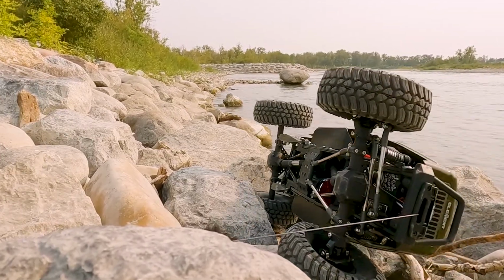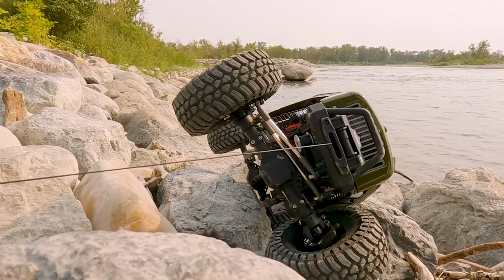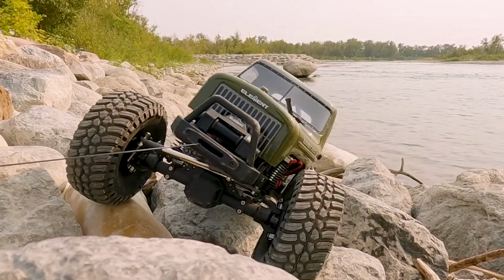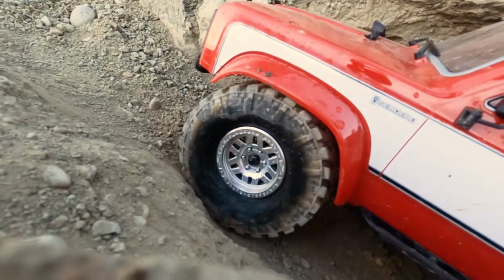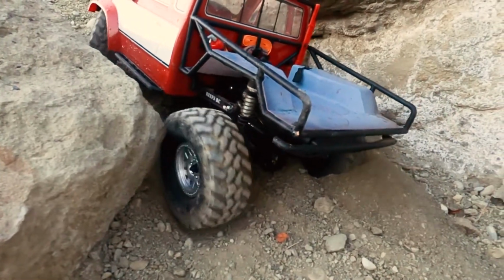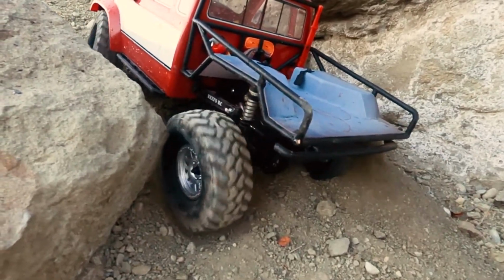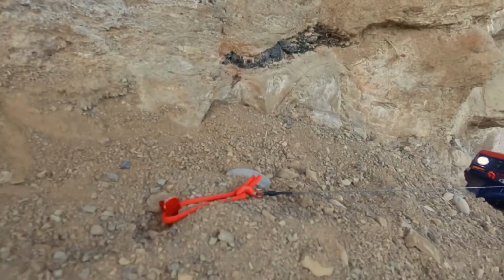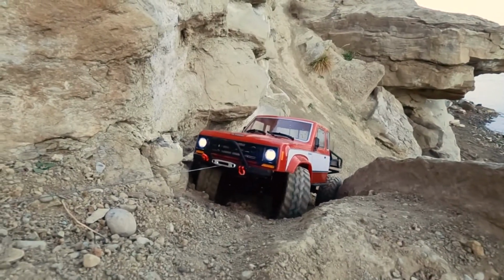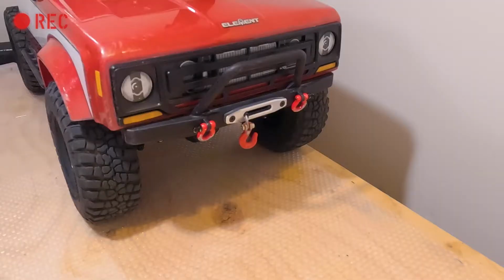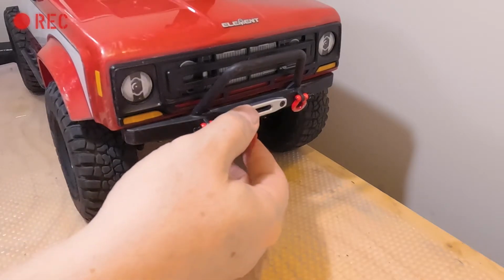Winching is fun, and in some contexts, like competitions, almost a necessity. Self-recovery winching in technical terrain often requires you to run the winch, steer, and use the throttle all at the same time. This is especially true of trucks with strong drag brake, hill hold, or FOC throttle matching functions. These trucks do not freewheel while winching.